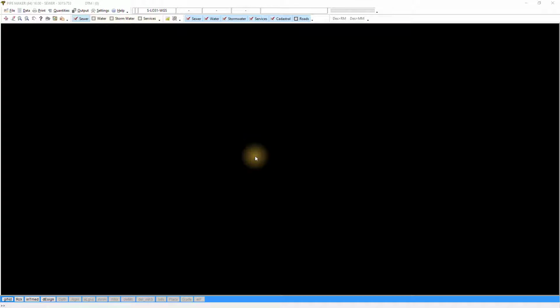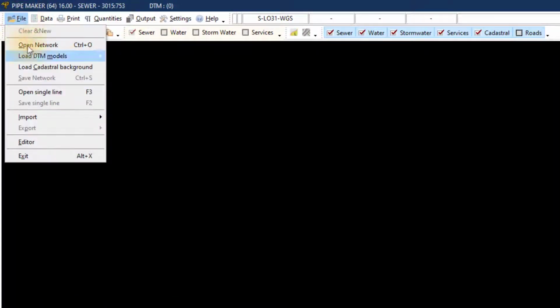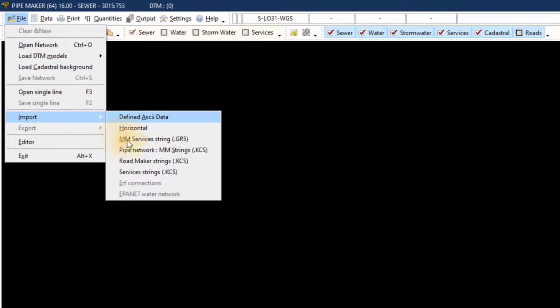Please watch Pipe Network Design Part 1, where we prepare all the files we use in this video. We start off selecting sewer design. Always do this first before you import the strings. When you start a new design, you will import your pipe strings. File, import, pipe network,